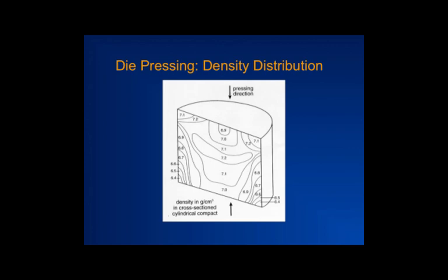This region has less powder, so to get the same final density, it has to shrink more. What is going to happen to the dimensions in this region compared to the dimensions over there? They are going to change. What about internal stresses? One region of the part wants to go one way, the other region wants to go another way. So you have internal stresses created, and you can have premature failure. That gives you an idea that this has to be controlled to some extent.